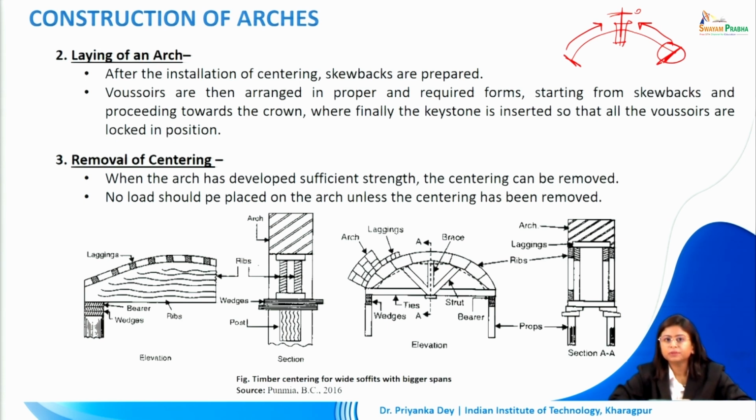The last step is the removal of the centering. When the arch has developed sufficient strength, the centering can be removed. No load should be placed on the arch unless the centering has been removed. So any form of superimposed loads we do not want to place directly on the arch. Any form of construction above the arch should be done after the centering has been removed, and that means that the arch has been finally prepped and has gained its sufficient strength. If you are using timber centering for wider soffits for bigger spans, in that case, in addition to the